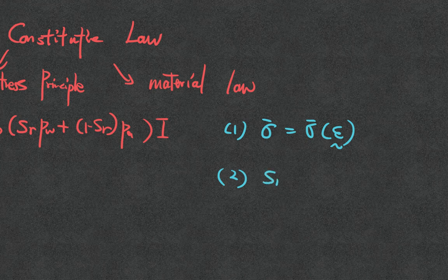Now, the second one is the retention behavior, which is, like what I said, writing it as the degree of saturation as a function of the suction, and sometimes also the porosity. And the porosity is related to the displacement itself. Okay, for simplicity, I'll just put the suction there. Can you all see the relationship between the porosity and the deformation of the solid? Okay, so there are very simple relationships, okay?